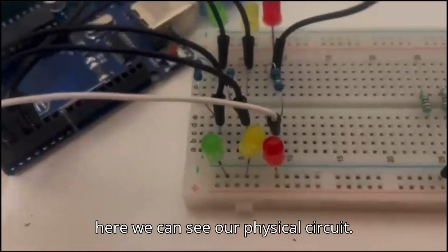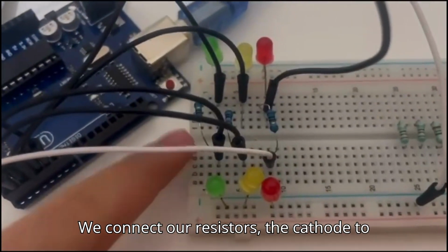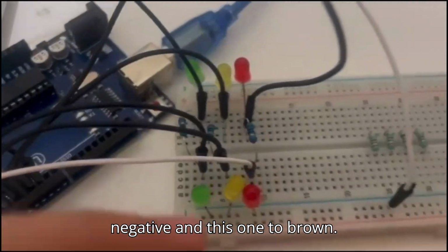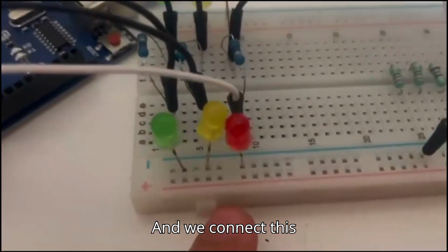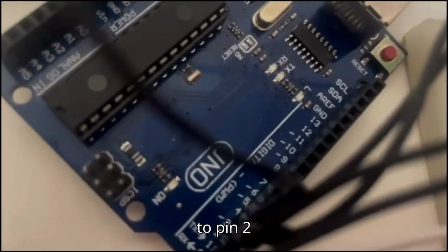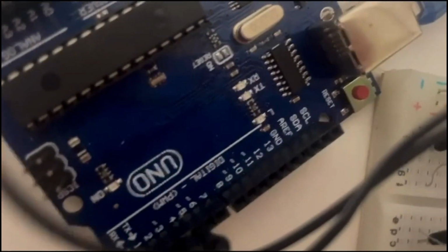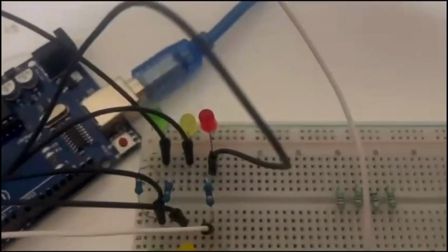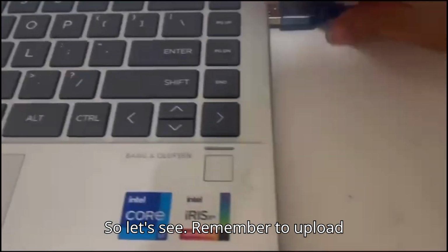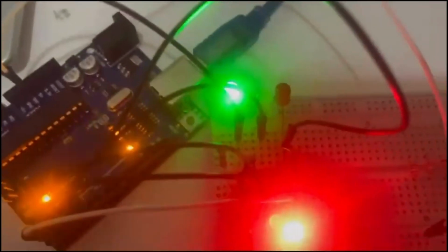Okay, here we can see our physical circuit. Here we have the LEDs, and on the other side we connect resistors, the cathode to negative, this one to ground, and we connect this side from pin 0 to pin 2, and these three from pin 3 to pin 5. So let's see. Now here we can see it.